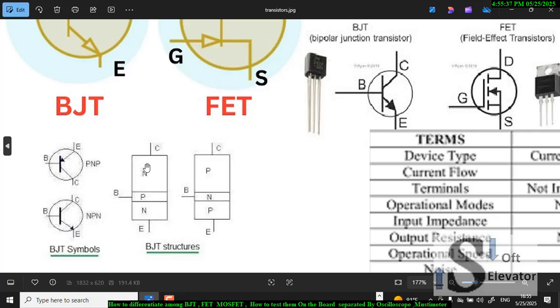If I reverse it, there will be an open circuit or higher resistance. If I put the black one here and the red one in this direction, there will be high resistance or maybe open. No current, no signal. Okay, no reading.